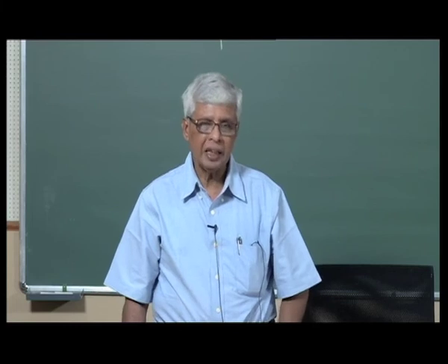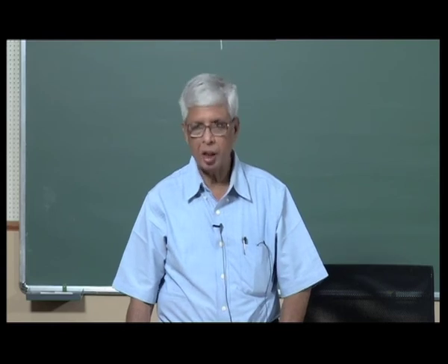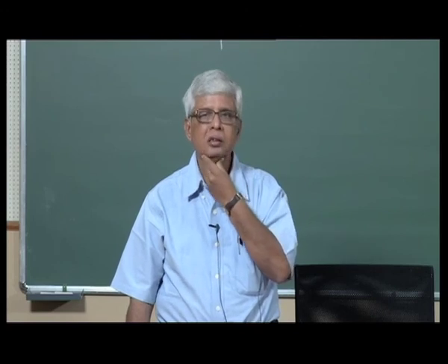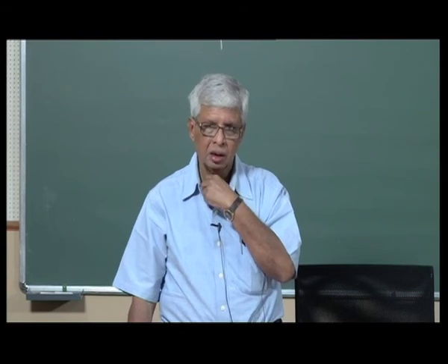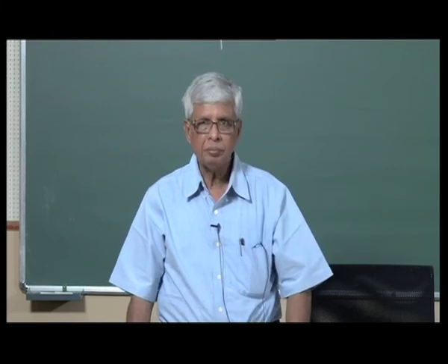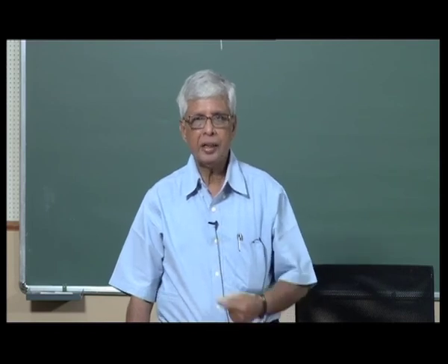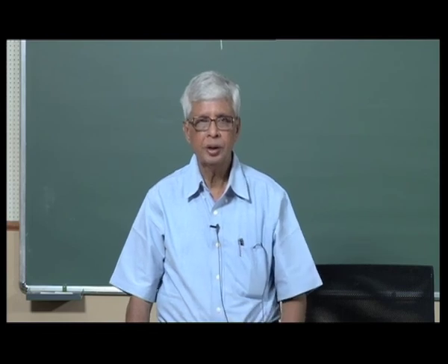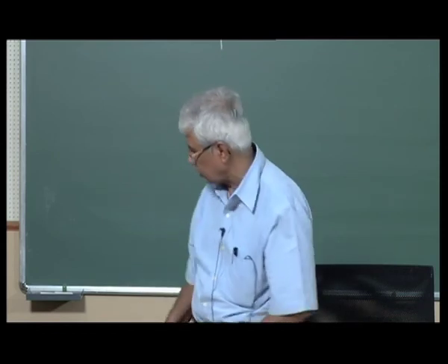Last class we talked about ROM, read only memories, which is a programmable logic device. What you have is, in a ROM, you have inputs, and all the min terms are generated. There are n inputs, there will be 2 power n min terms, and then you have an OR gate array. These min terms are connected as required to get different outputs. For example, we said you have n inputs and m outputs.